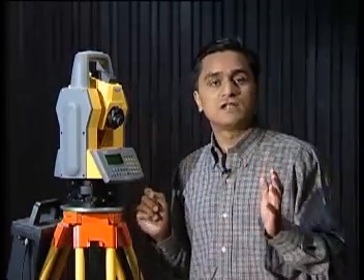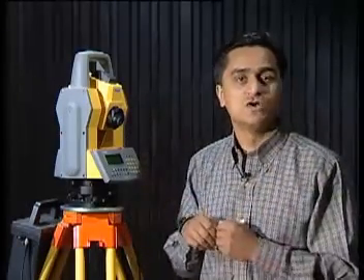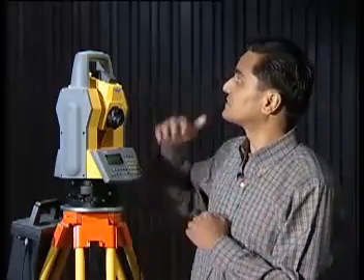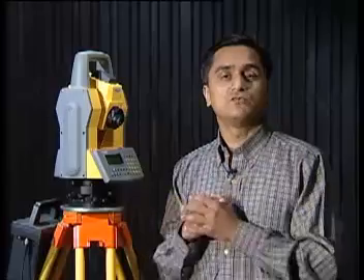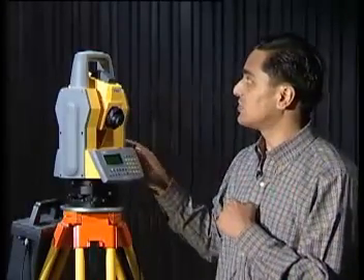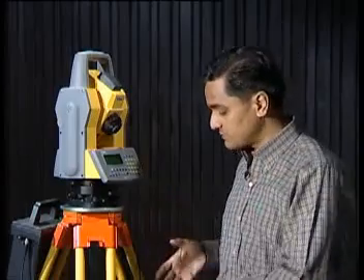This reflector-less method of measuring the distances or coordinates is very, very useful. For example, in this room, if we want to measure up there in the rooftop, the ceiling, so any other method will fail. But in the reflector-less, what we can do, I can take this dot to the ceiling, it goes to the ceiling, and that's the point where I want to measure the coordinates of. Now you can see that point, I'm moving that point, and this dot in your screen is moving. So for this point, for example, I need the coordinates with reference to the point where I'm standing.